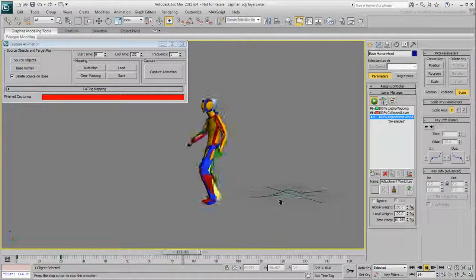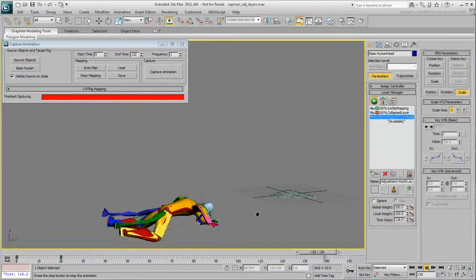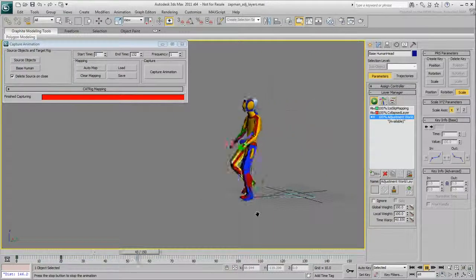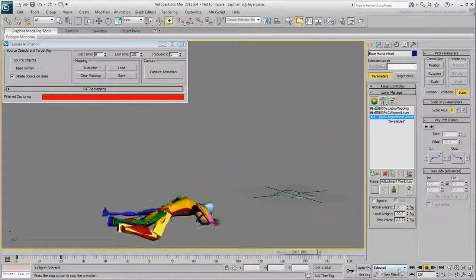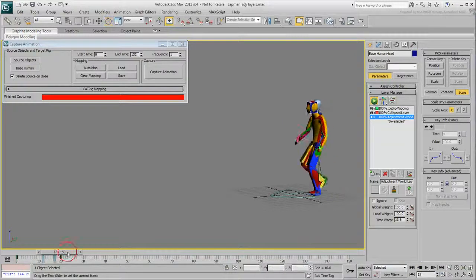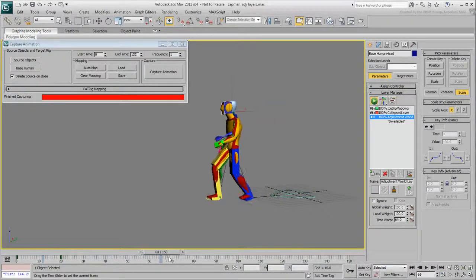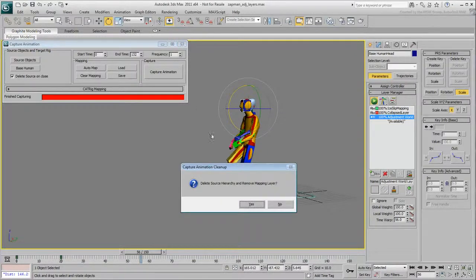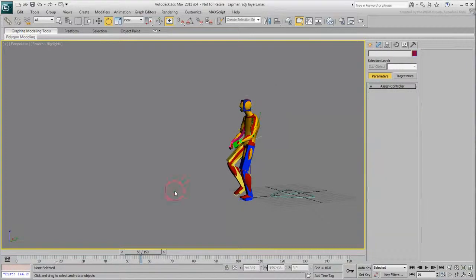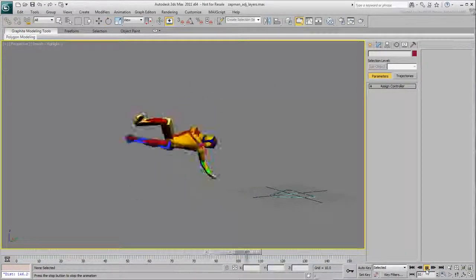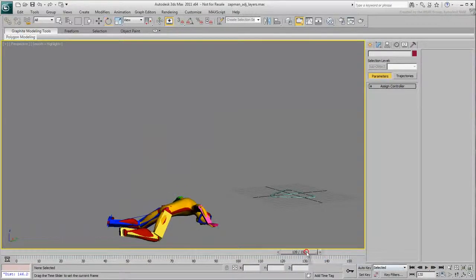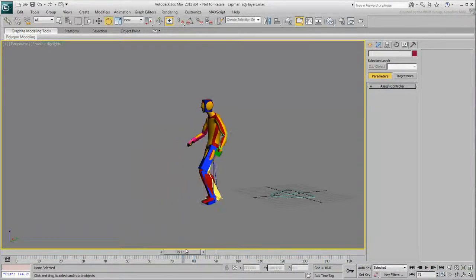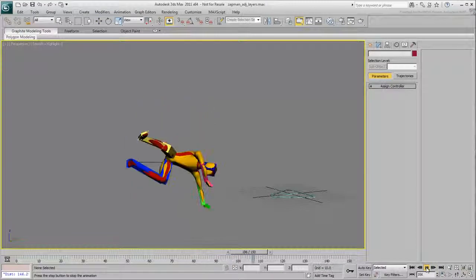At this time, the motion capture skeleton that was used for retargeting your rig is still in the scene but is no longer needed. You have already baked the animation to the skeleton and adjusted the animation through the adjustment layer. As you close the Capture Animation dialog, a warning appears. Click Yes to remove the retargeting mapping information and to get rid of the no longer needed skeleton. You can keep fine-tuning the existing adjustment layer or add more as they all work in an additive, non-destructive way.